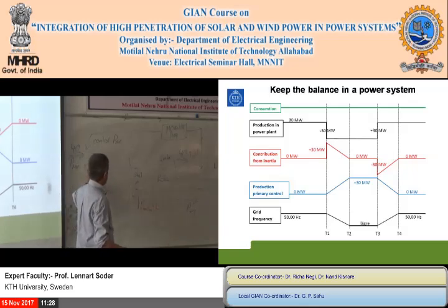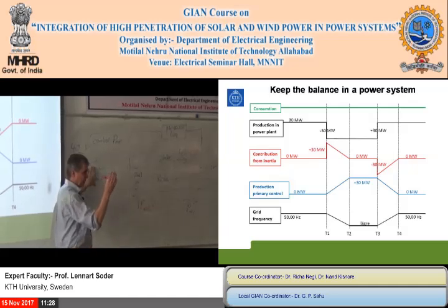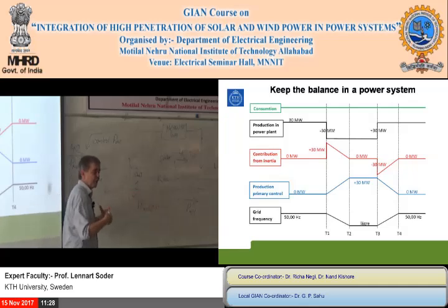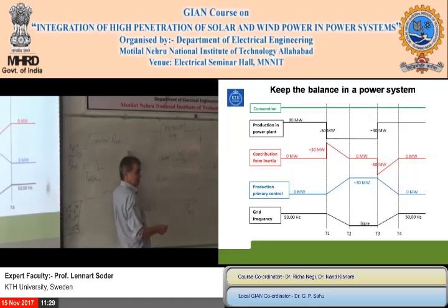But if you have a gas turbine of some kind, or a steam turbine, the steam is going through it, and then you make it rotate. And if you don't have the steam and you want this to rotate, then you are in reality moving air instead. So if you just have this rotating in the air, then of course it will consume a huge amount of power because it's a big fan, which is not the idea. So because of that, if you have a gas turbine and you want to use it as only a synchronous machine, then you have to disconnect it here.